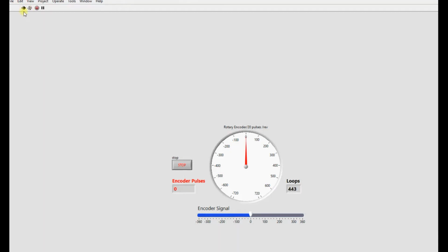Okay, everything starts at 0, and here I'm turning it one click, and that click is actually a mechanical detent. So there's something mechanical in there, probably a spring and a hole, that every time you move it one turn or one pulse, you'll see an 18 degree change. So I guess it's because I didn't go completely one direction. Let me start again. 0.